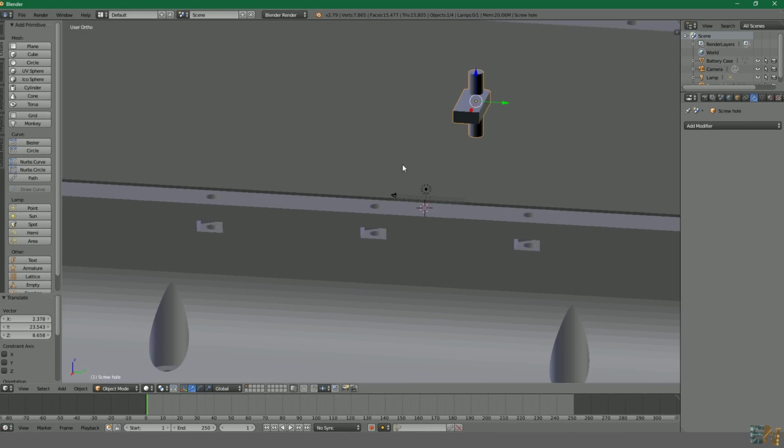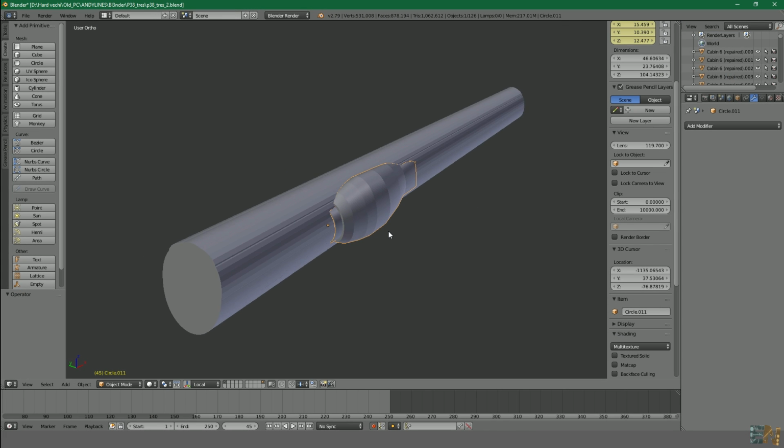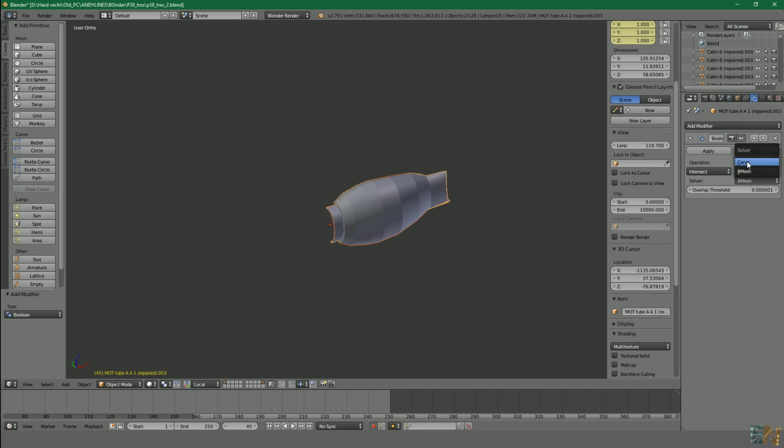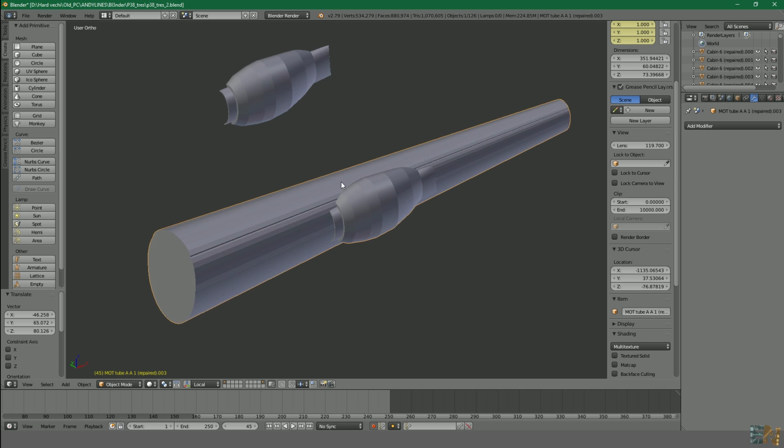But instead of subtracting with booleans, you can make a union. So here we have another two objects. As before, I select one and then the other. I add new booleans, I change the mode to carve, but now select the union operation. That will unify these parts exactly on the points where they touch.